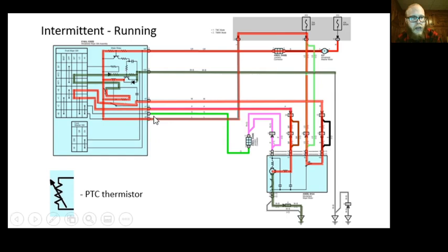Or actually, this wire's for power end of the switch. So if any of the other speeds work, it's nothing wrong with that. This wire's for high speed. See how it goes to the high speed brush. This wire's for low speed, and park for that matter. So if it has low speed, we know that's not the issue.